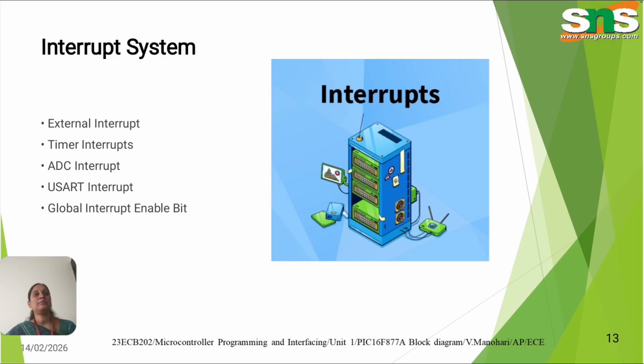Next, interrupts. Interrupts allow the controller to respond immediately to events. PIC supports external interrupt, timer interrupt, ADC interrupt, and communication interrupt. When an interrupt occurs, execution jumps to a special interrupt service routine and then returns back.